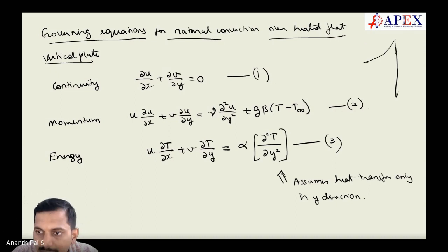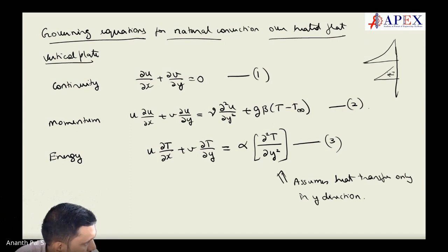So there is self similarity in temperatures. You see that? So here it may be something like this. Agreed. But these are self similar, and the temperature diffusion in the x direction is very minor. The diffusion is actually in the y direction only, not in the x direction, because the temperature difference is much higher in the y direction rather than the x direction.